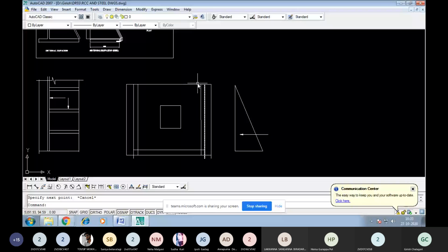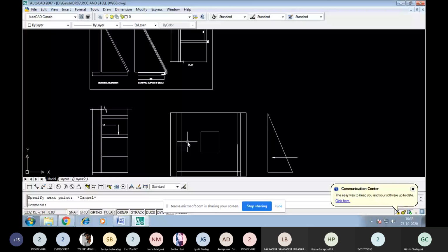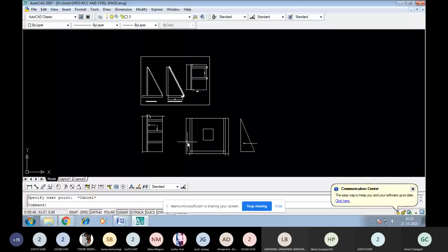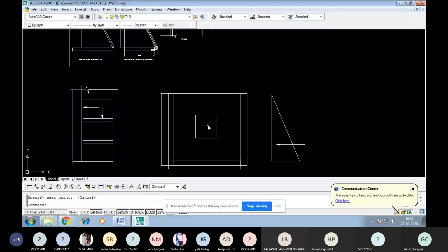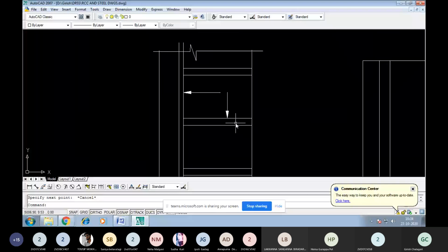Since it is designed as a slab, a small component will be taken. The thickness of the stem gets reduced. It will be straight with the same thickness throughout, without any taper dimensions like we did in a retaining wall. In a similar fashion, when we look at the bottom heel slab, it is also connected with the counterforts on either side and with the stem on one side; it is free on the other.